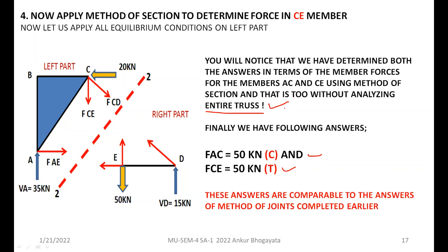If it is asked to find the member forces on X and Y members directly in the truss, without any delay you should start using the method of sections. But if the instruction is like this: given below is a truss example, calculate the member forces in all members, then I would advise you to use the method of joints, because without it you will not be in a position to calculate all the member forces.